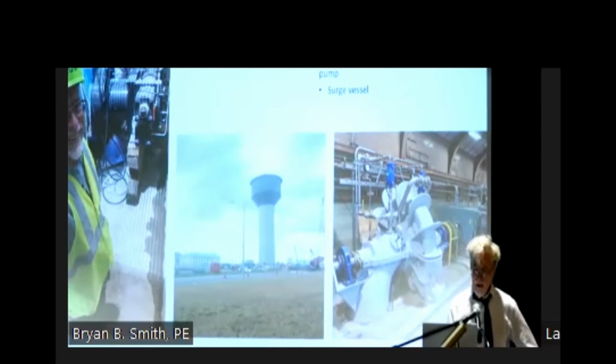So we look at this and we don't rely just on the pressure transmitters with regard to the proof of design. We put in high-speed pressure transmitters so we can see the cause and effect of turning on and off that pump within your system. And we're recording that pressure transient at 100 times a second, so we can see that negative wave going out and coming back.